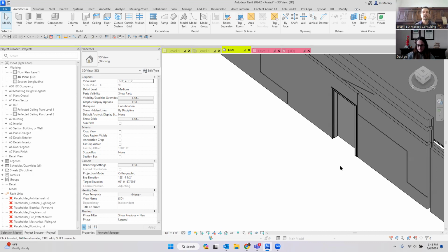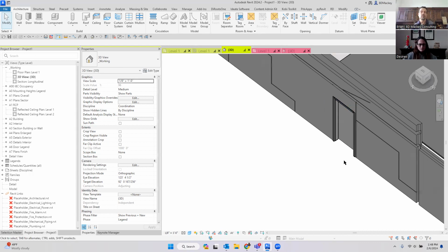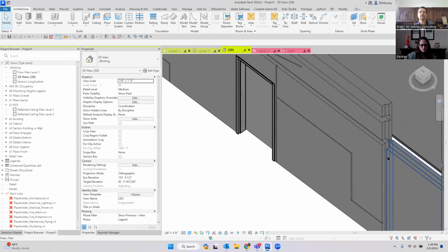Curtain walls are probably going to be more understood by everybody. But also, if I want a 1/2 inch reveal, that means I'm now either putting in a mullion that's very, very thin to look like that 1/2 inch reveal, or calling the mullion my backer rod and sealant, which I've done before as well. So you can go through and do that.